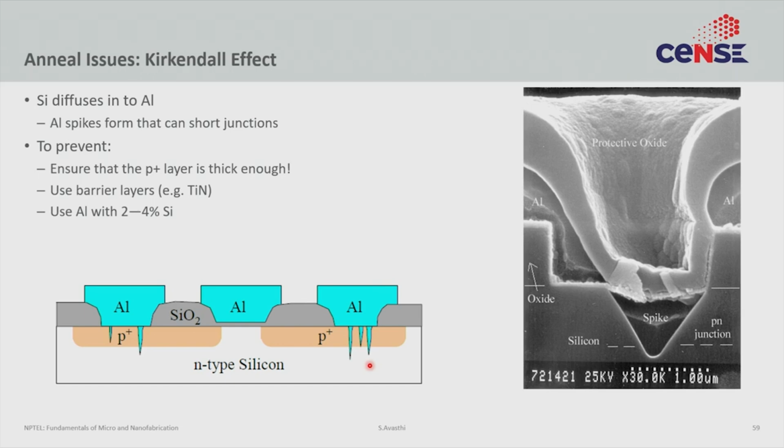One, if you take this system after deposition of metal to higher temperatures, and two, if your p plus regions are very thin. So, supposing you are doing rapid thermal annealing of very shallow implants, after that be very careful in using aluminum. If you directly do aluminum and do high temperatures, you might have a short. Even at low temperatures, you might have a short.